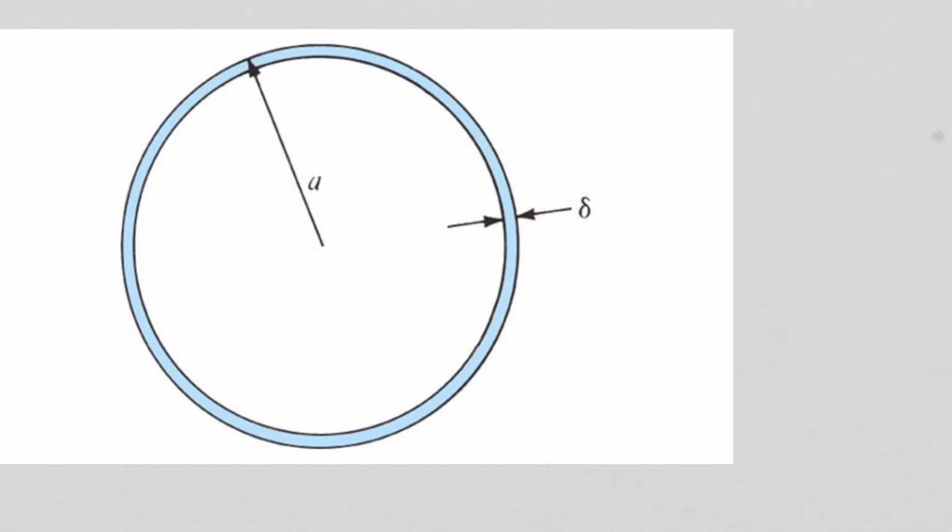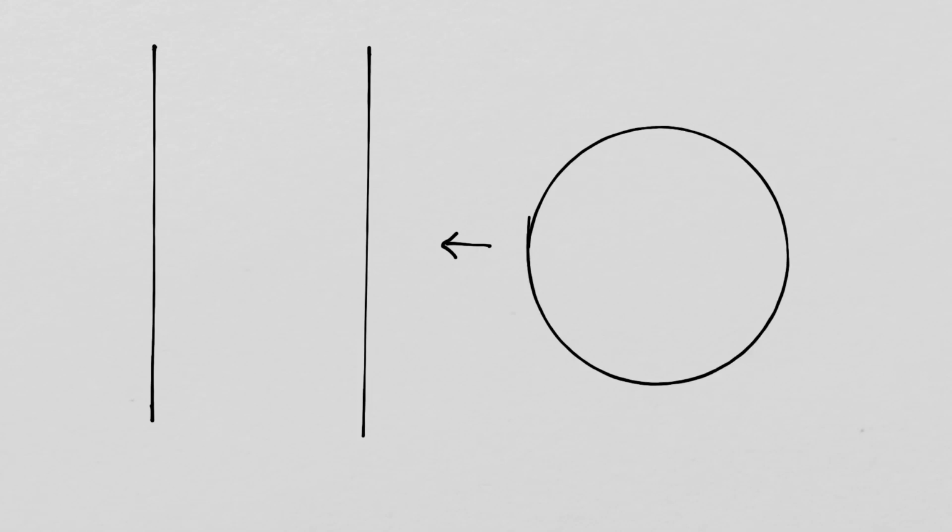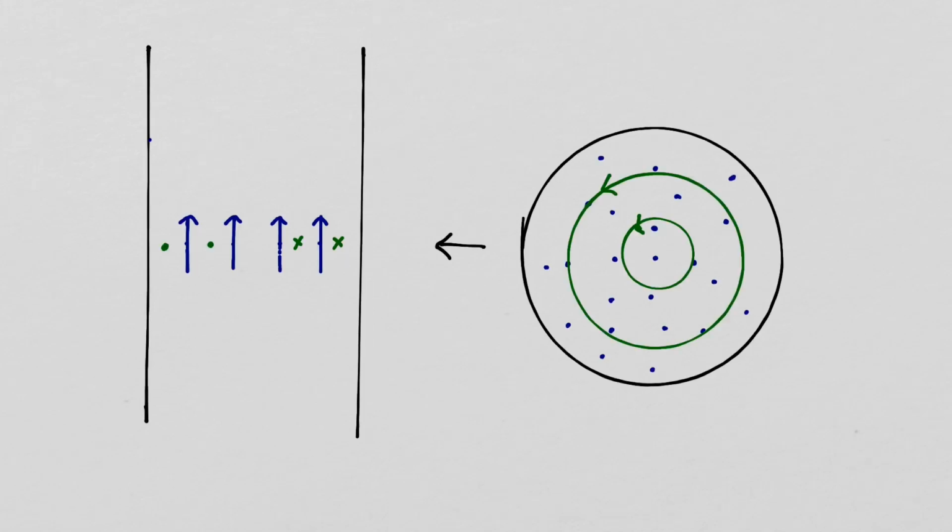Here we have a wire, and here is a cross-section looking through the wire. Here I'm showing a current flowing in the wire, so looking through the cross-section we see the current is flowing up out of the page. The magnetic field intensity lines from this current coming out of the page will be these counterclockwise circles, and over here that means on the right hand side the magnetic field intensity lines will be going into the page, and on the left hand side out of the page.